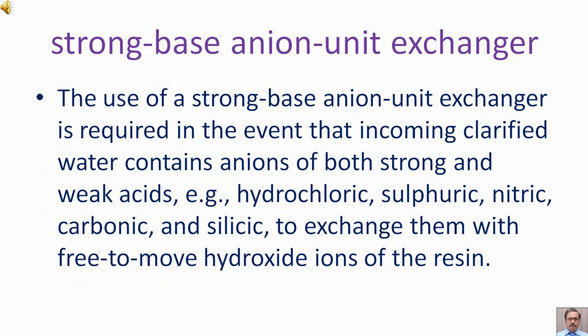The use of a strong base anion exchanger is required in the event that incoming clarified water contains anions of both strong and weak acids, that is, hydrochloric, sulfuric, nitric, carbonic, and silicic, to exchange them with free to move hydroxide ions of the resin.